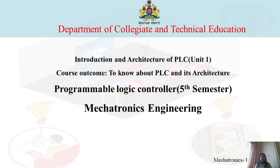Next, we have seen how the classification of PLCs is made. We have divided into two types, that is modular PLC and compact PLC. In the modular PLC, there will be an extension of the modules. It will permit to add the units, that is IO unit, memory unit, etc. In the modular PLC, all the components are independent of each other. We are connecting manually all the components and making the PLC system. If any fault or error occurs, to replace and to repair is very easy in case of modular PLC.